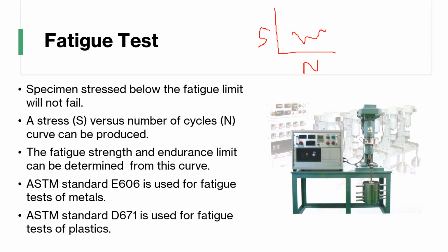We will be using ASTM standard E606. We also use ASTM standard D671. The very first one, E606, is for metals, and D671 is for your plastic specimen. From here, we can get the stress limit that this material can stand.